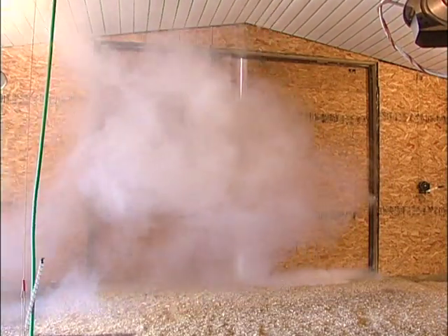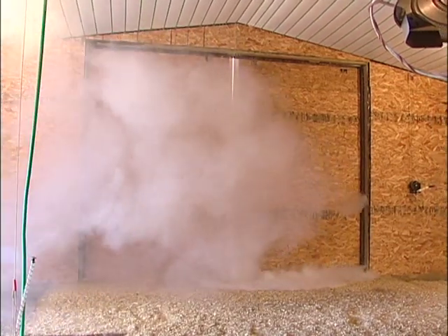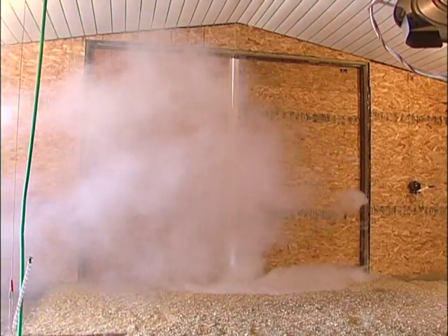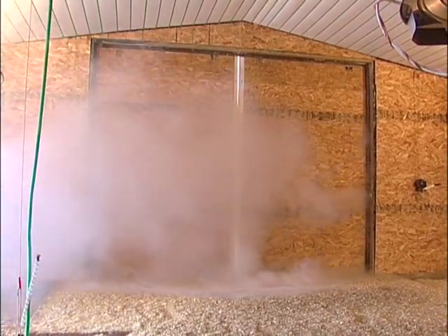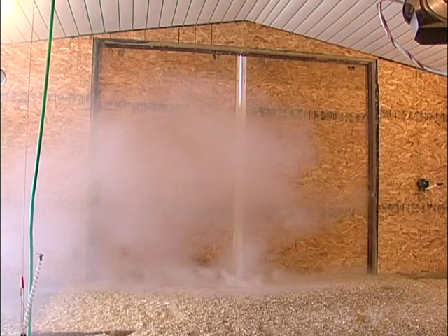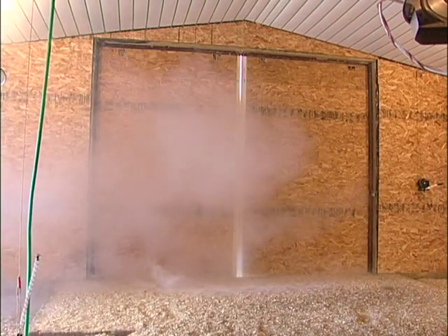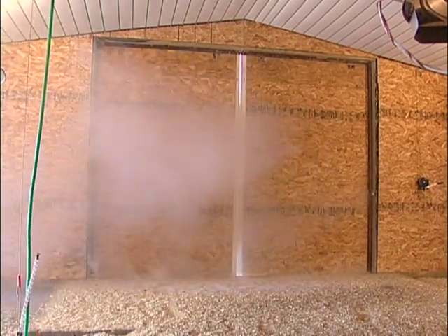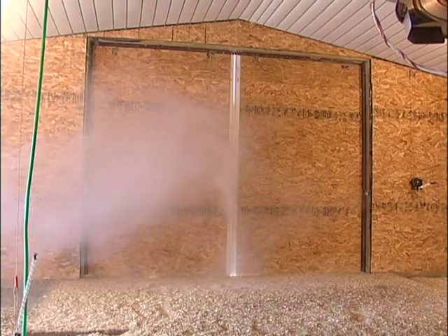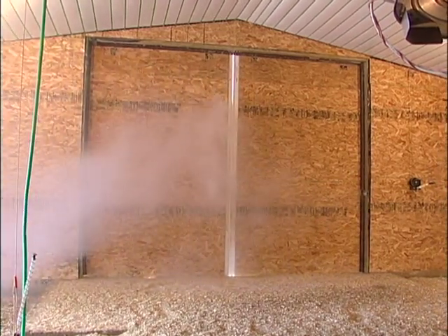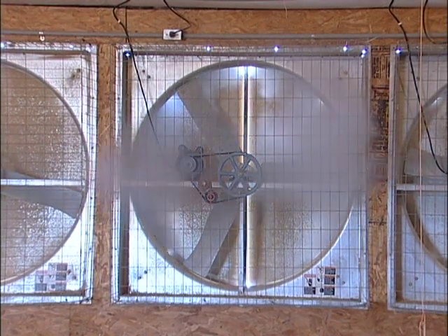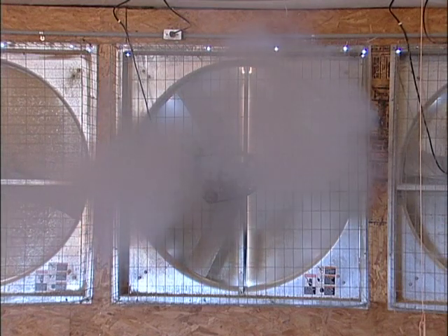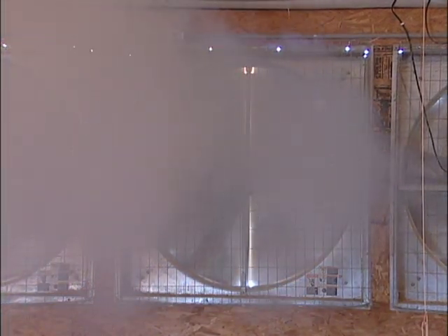And you can see that the side all around the door, in the middle of the door and under the door, it's severely leaking. And we're gonna go from here to one of these sidewall fans. The sidewall fans in this case have the baffle type or the gull wing type shutters, and they don't leak as bad as a regular shutter. We take for granted that those shutters don't leak very much, but look at the air that's coming around those shutters.